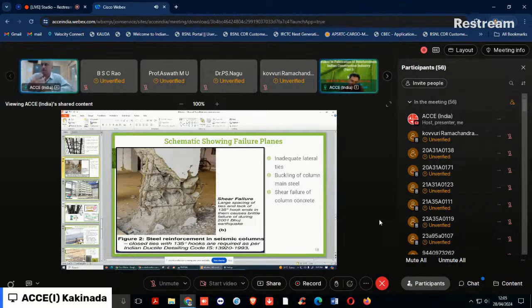Now the stress transfer is from the outer shell concrete to the inner core concrete, and the inner core is trying to take the load that was lost by the shell concrete. Due to this, the core concrete is subjected to higher compressive stress, and it is now trying to crush itself under the increased axial compressive stress. After the crushing, in a brittle manner, the loss of compressive strength carrying capacity of the shell concrete has to be compensated by the core concrete. Plus, there is an additional burden on the longitudinal main steel.